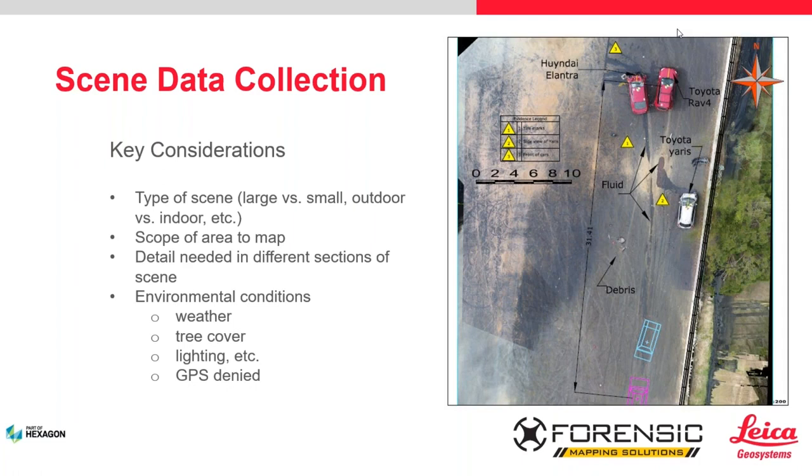Okay. The other thing to think about too is that we're also used to mapping, whether it's with a total station or what's called RTK GPS or GNSS, which is a network corrected GPS measurement. So the accuracy is a couple hundredths of a foot. As we all know, regular GPS is 3 to 5 meters or 10 to 15 feet at its best. So that's why we need to have the corrected GPS. And those are other tools that you could use at your scene. And all of this can be incorporated into your maps.